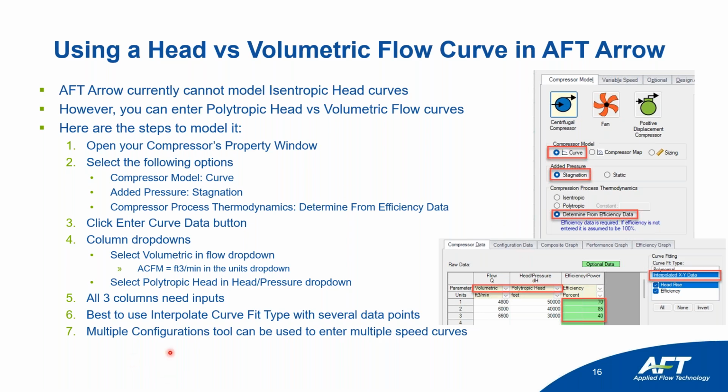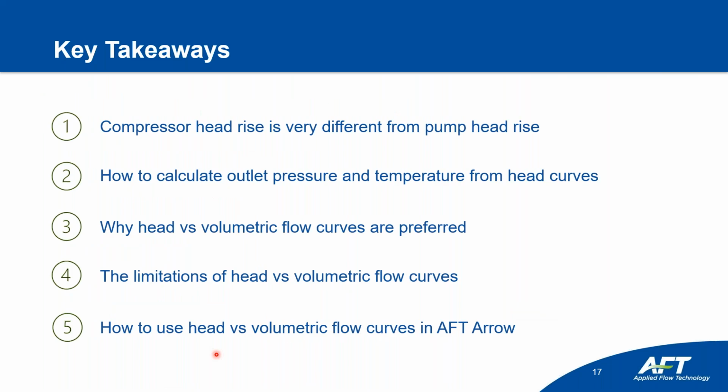Oh, and also, we have a multiple configuration feature. You can find that on docs.aft.com as well, and that can help you enter multiple speed curves for your head versus inlet volumetric flow. So that's all the details.